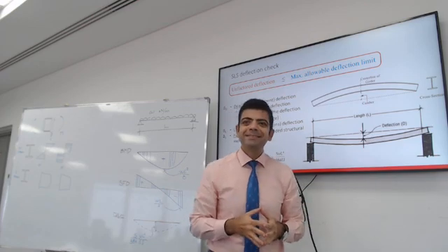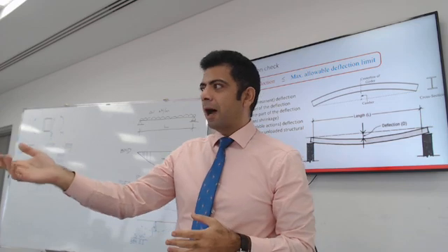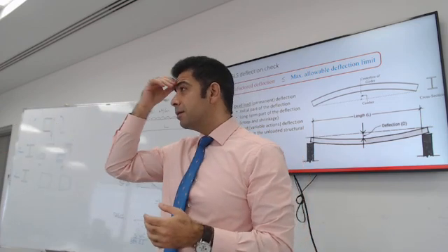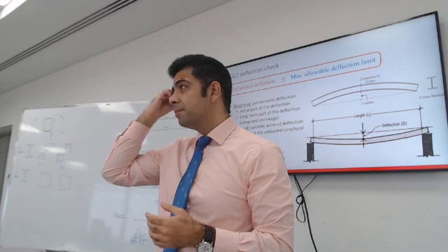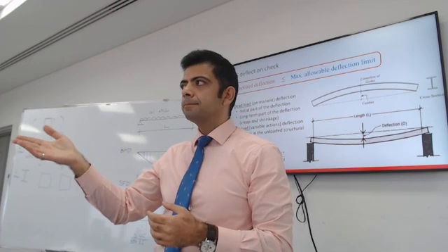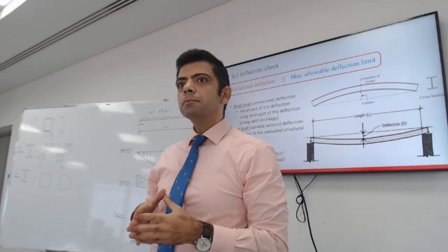It depends on the camber, according to the load, right? If there is not much deflection, we will push it straight. But if there is a huge deflection that we need to balance, then we will make a camber.